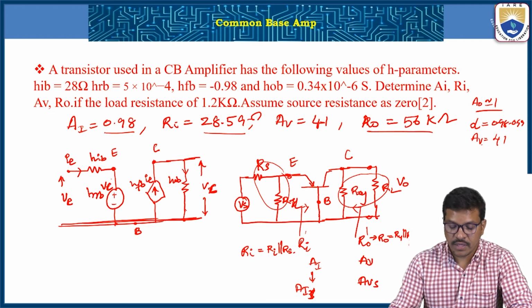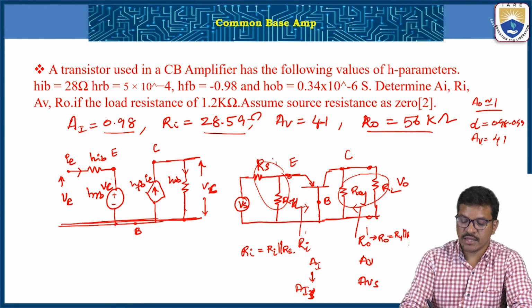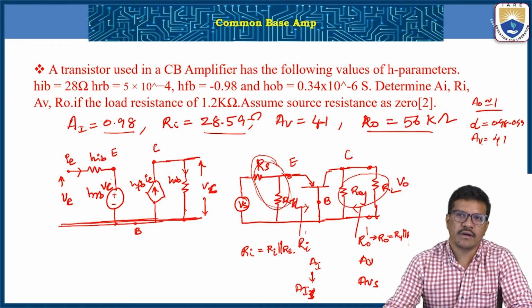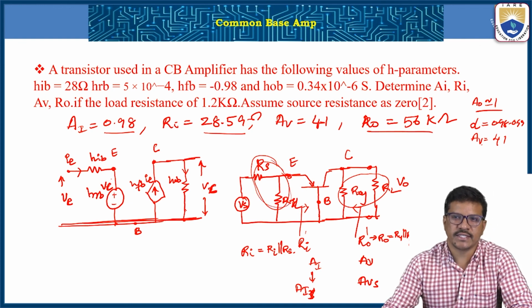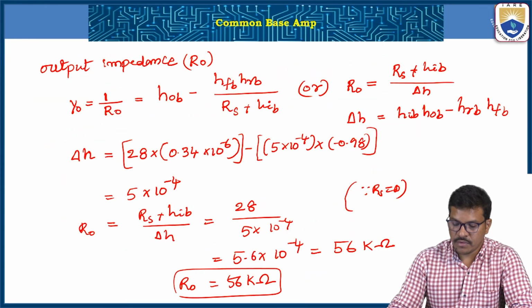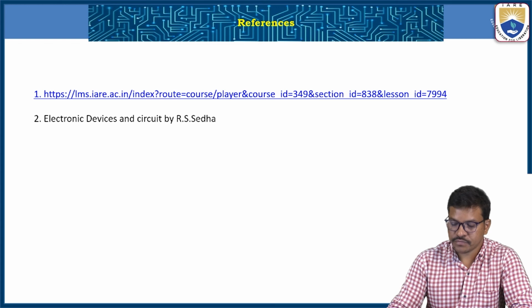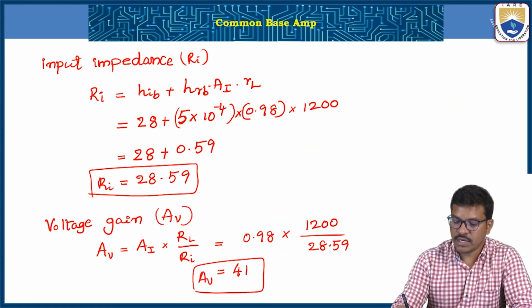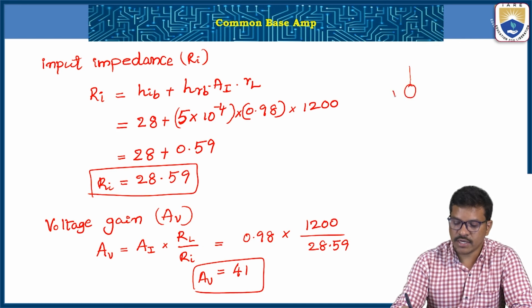So in this way, when we connect an extra source resistance, we are not assuming that the source resistance is 0, then we can consider RS. When we consider RS, the final input impedance value changes. If RS is considered, the total overall voltage gain, the external voltage source Vs connected with RS.